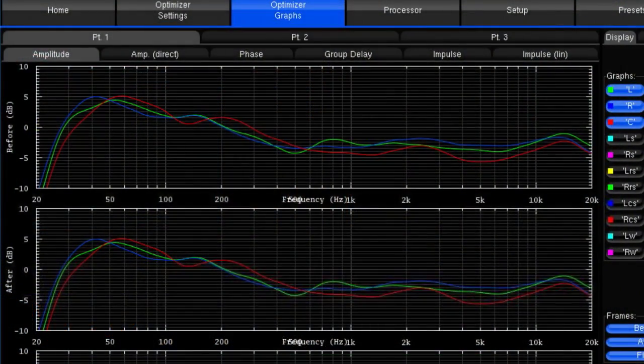And so, a qualified engineer needs to intercede and change the target curve. And this is what I'm saying: that measured sound that we just looked at ought to inform the target curve, because that tells you what the directivity of that speaker does within the acoustic signature of this room.